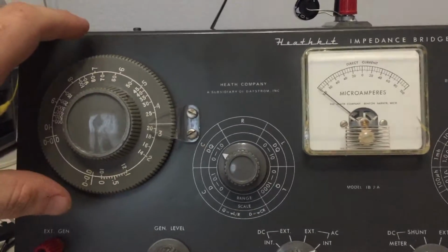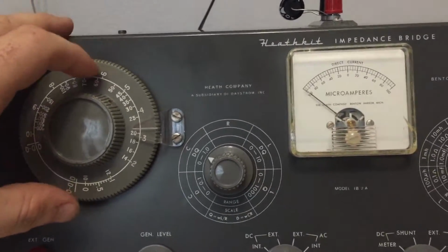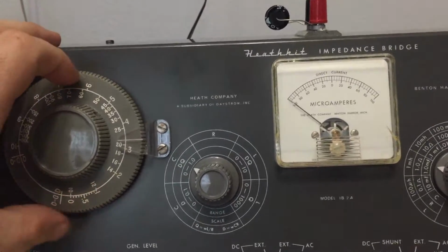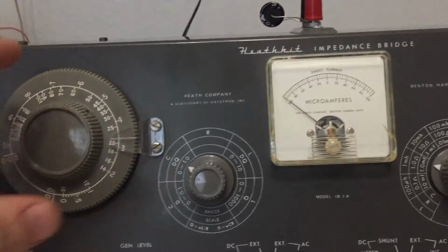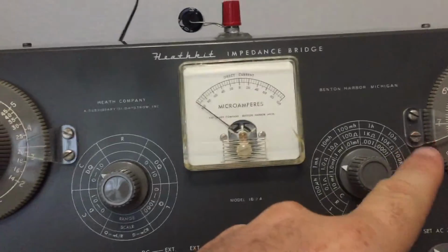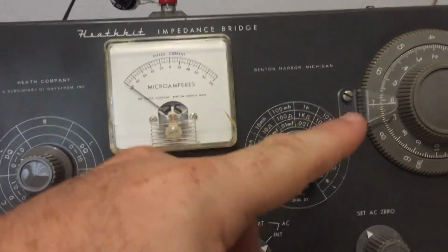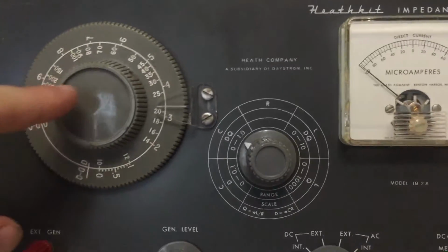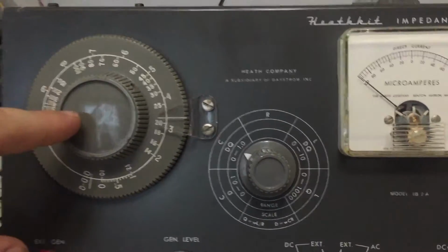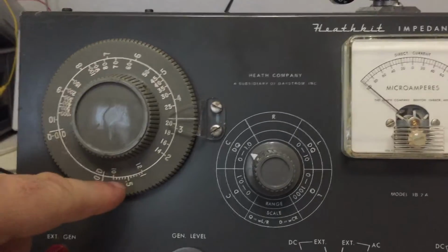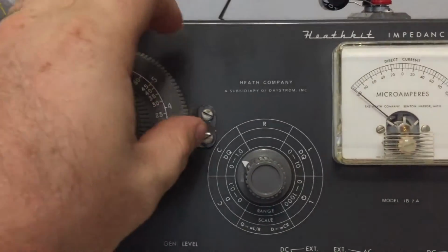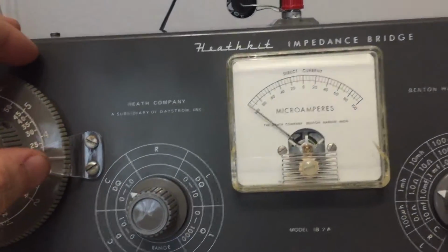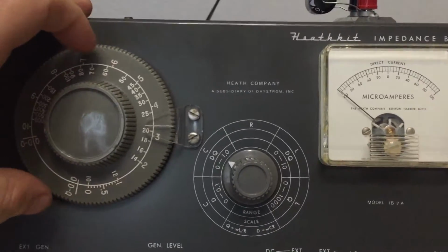The other way, a bit more technical, talks about measuring the back of the unit. They have a convoluted way of using this to measure exactly 160 ohms, but you could use an actual multimeter to measure the back of the potentiometer for exactly 160 ohms, and then when you had that, you would turn this and align this to 0, right? And that would be actually 0.